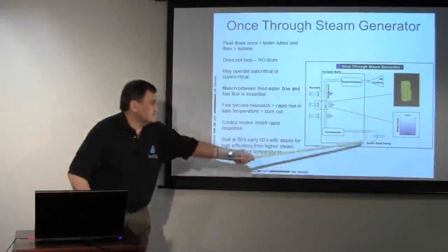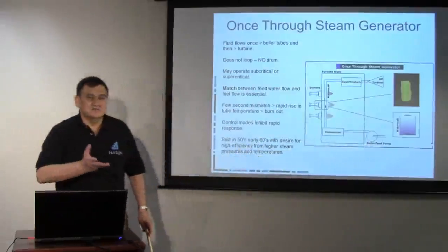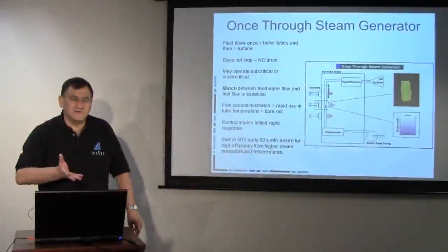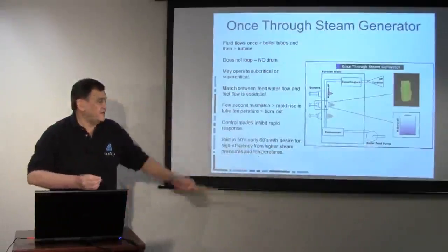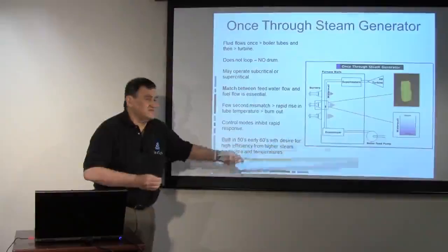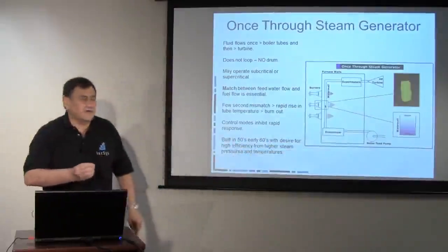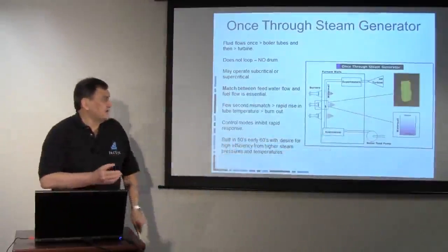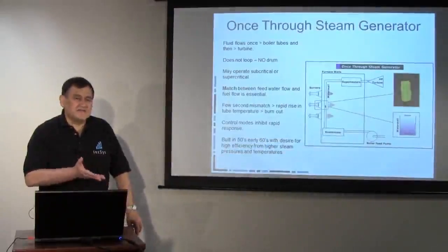And as you're going from that 0 output to minimum output, the operator is balancing these things typically manually. Sometimes the instrumentation does not work very well at the lower temperatures and the lower fuel and water feed rates. And so there's a desire from the operator to get that system up to the minimum load as quickly as possible, and then have all the control systems take over.